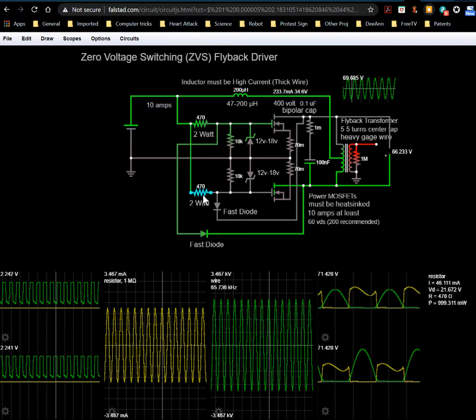It's going through here, and basically is going through that diode straight to ground. So that means ground plus 0.6 volts or whatever, and this is a little above ground because it's not 0 ohms, but roughly 1 volt or so. In fact, you can see in this case it was 2 volts at this point in the circuit,